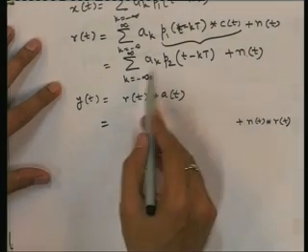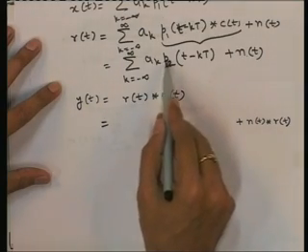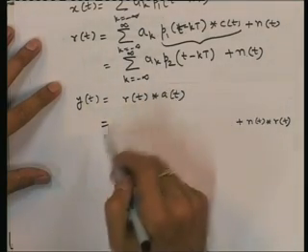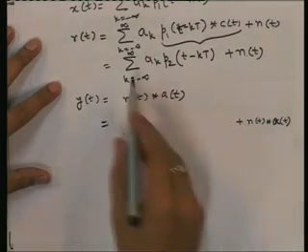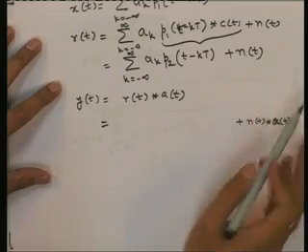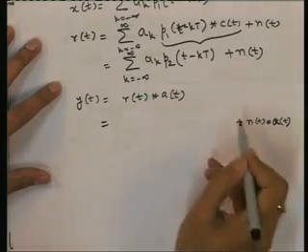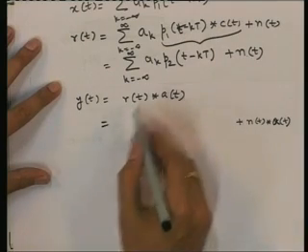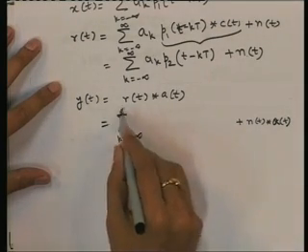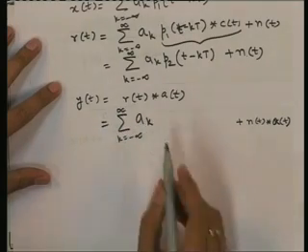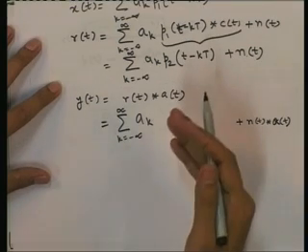and then here this summation convolution with r(t), but this convolution can be taken inside the summation again. Sorry, r(t) is this, so convolution with a(t). So convolution with a(t) with the noise, and then convolution with a(t) of this summation. So that convolution with a(t) can be taken inside, and then we have a_k as it is, then p2(t minus kT) convolution a(t), that can be written as another pulse.